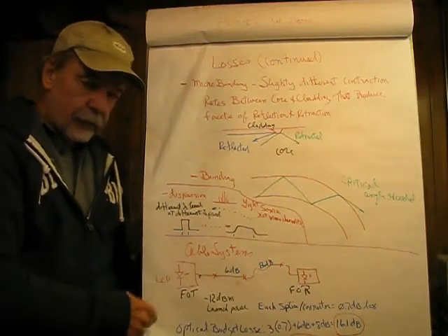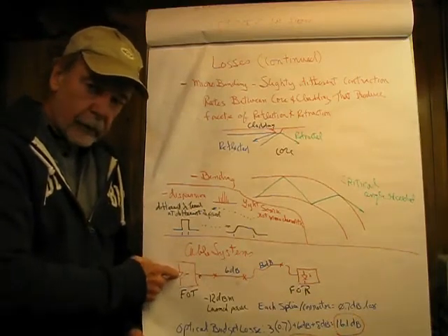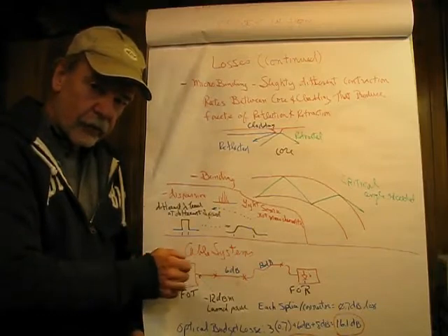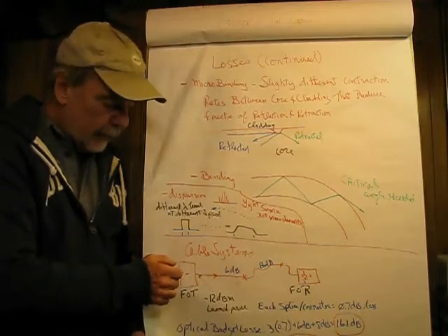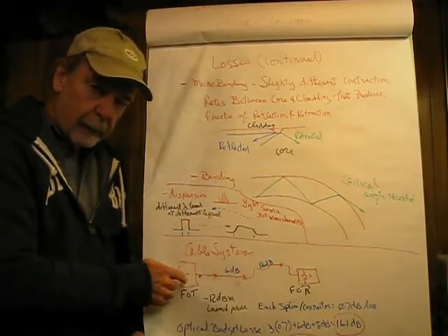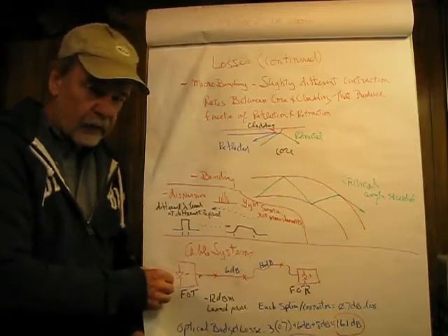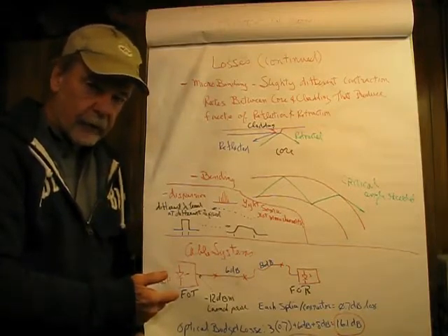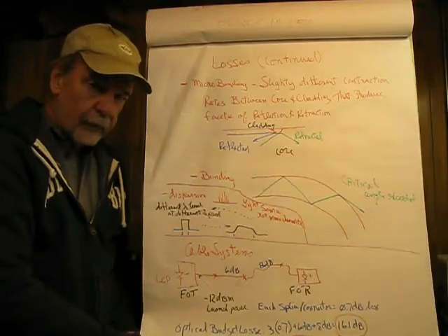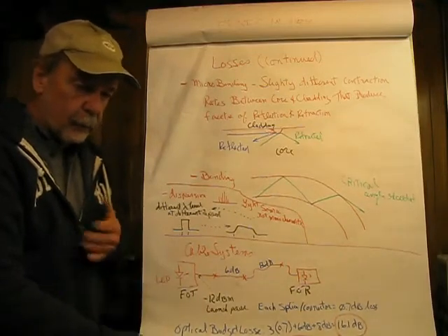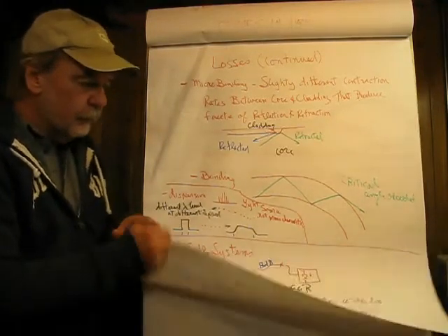In laser-based systems, they have a sniffer diode in the laser package, which samples the light. And as that begins to fail, the output of the sniffer diode drops, and it'll actually bring an alarm before the end of life. So there are wear-out phenomena that go on in this. It's just not put it in and it's going to live forever.